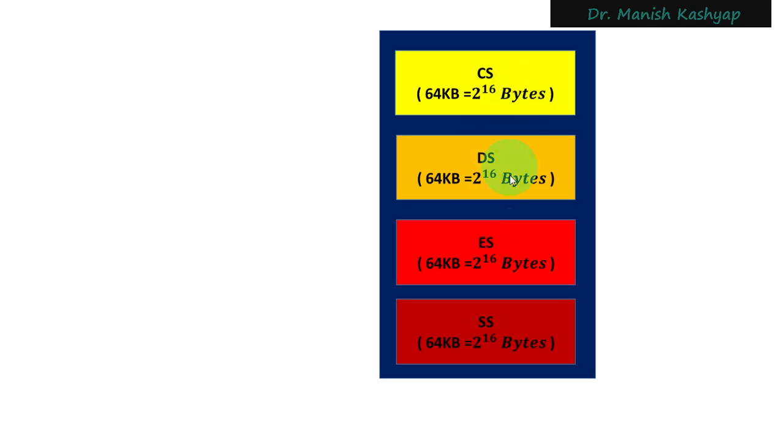This is a very elegant way of actually keeping your code segment, data segment, extra segment, and stack segment separately. Now, this extra segment can be used for any general purpose. You can keep some data into it, you can keep code into it, you can also write some stack into it, right? So that is also there. So this is a general introduction to the externally interfaced memory of 8086, which is 1 megabyte in its complete extent.